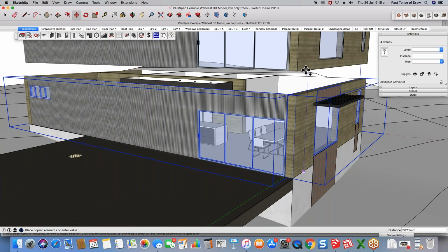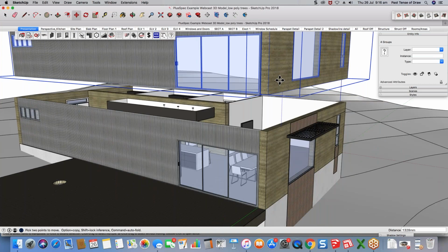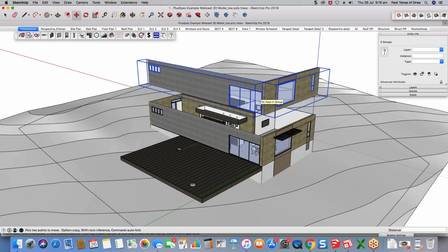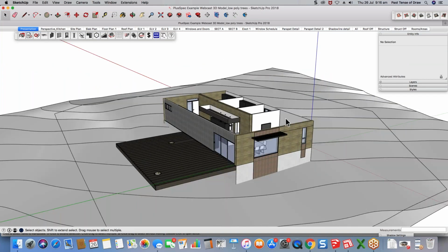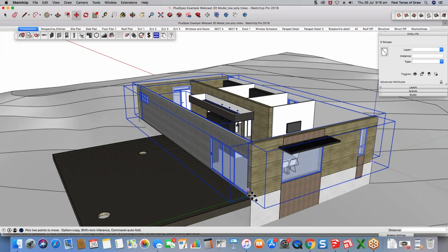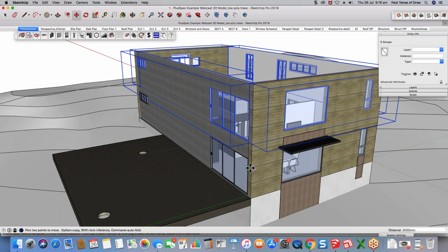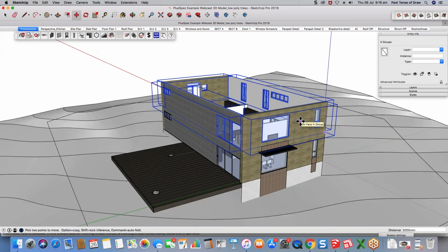This is giving you the ability to determine where you want to place things. Now, again, I could delete that. I didn't actually select all my walls, but if I hold down my shift key and select the different walls that I want to put in there, I can then do it accurately and position them again on the blue axis. So the blue axis is what you're using to determine your heights.